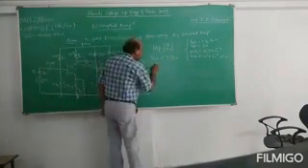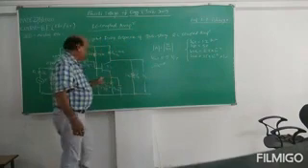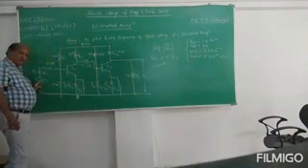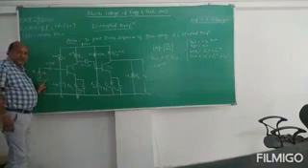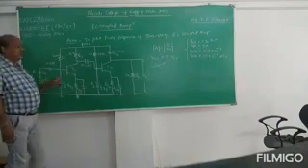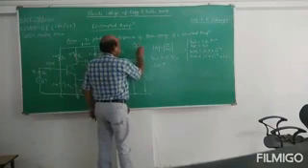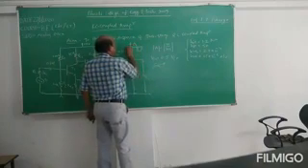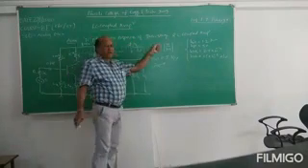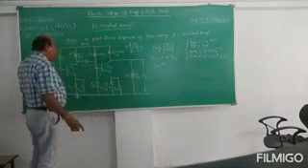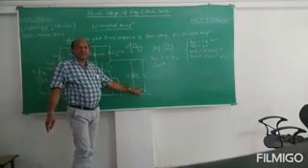And now we will vary the input frequency, this F. So F should be varied continuously. We will use the function generator here, and from the function generator we will take the sine wave, with its amplitude fixed at 0.5 volt peak to peak. So we will take this 0.5 volt and vary this frequency. The input frequency should be varied from the function generator, and we measure the output voltage on the second channel of the CRO.